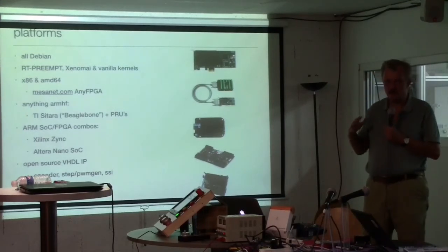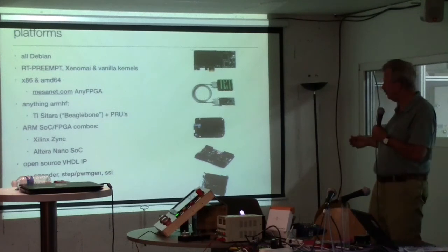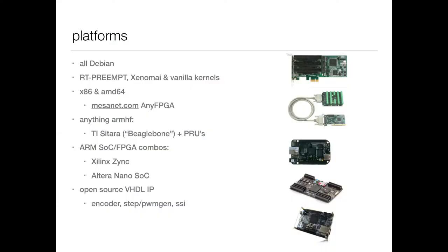I hope we got across the principle of how you configure that thing. You think up a circuit, you map it to HAL components, you wire them up, and then you run them. Now, just to wrap this up, on what platform does this run? Unfortunately, as a project, we are being perceived as a BeagleBone project, which is not the case. It is actually portable over several real-time Linux kernels and a whole range of architectures.